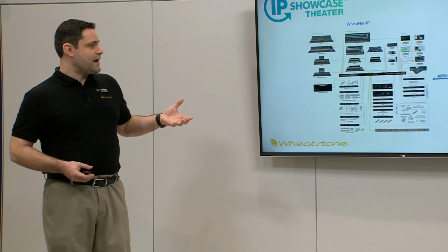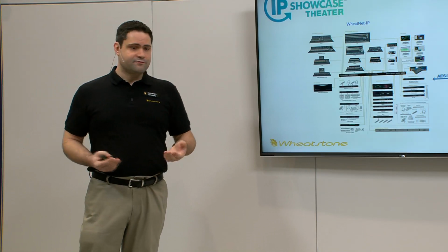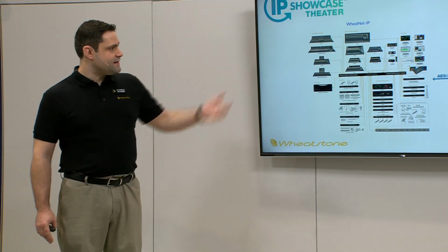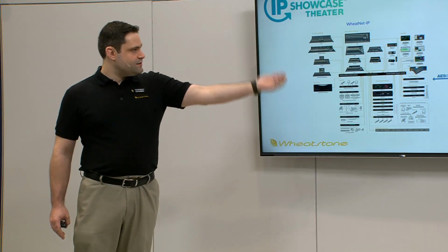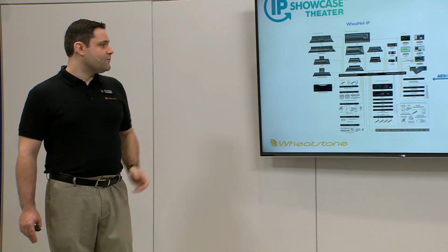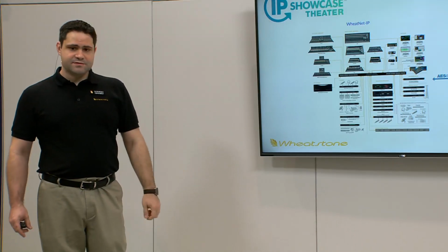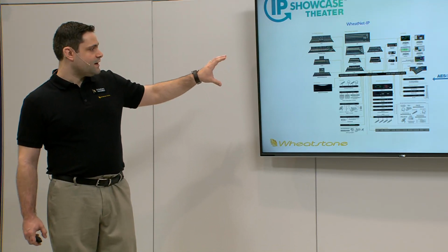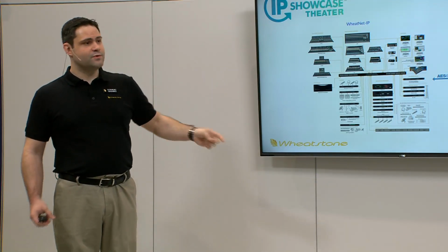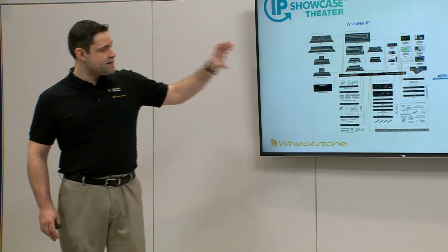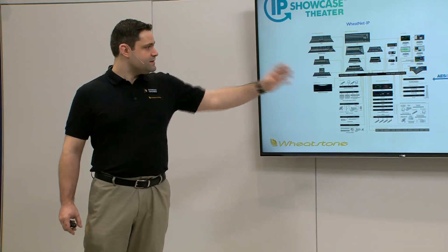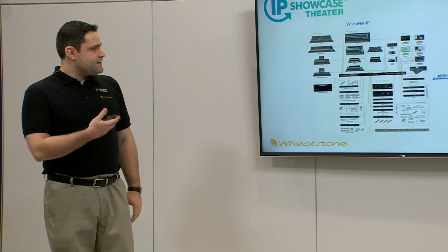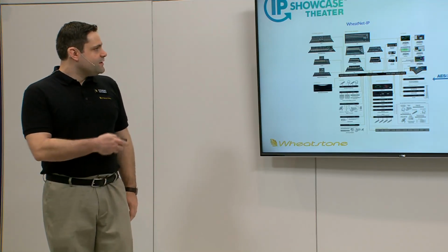But how do you use that with other vendors? If, for instance, you're trying to receive data from a Dante device, maybe there's microphones at a remote site, or maybe there's some playout speakers at a remote site that you need to access. You can still use the network that you're used to, with whatever network that may be, but use AES67 to get to those other devices. And that's kind of what we're trying to do here.